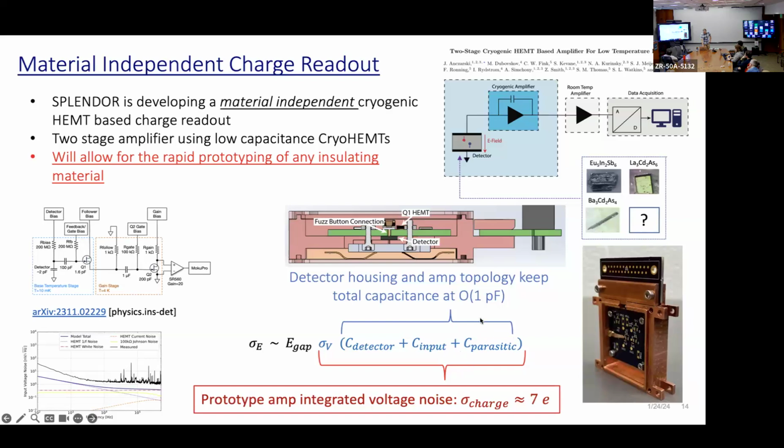And then the big one that's really hard for a cryogenic amplifier is the parasitic capacitance. So this whole thing is in a dilution fridge. The sample itself needs to run on the mixing chamber. These HEMTs are designed to run at 4 Kelvin. And so the distance between those two stages is this big. So you have at least a meter of cabling that you have to account for, which I think for a standard twisted pair would be probably microfarads of capacitance. So when the other things are picofarads, that would completely destroy the signal.